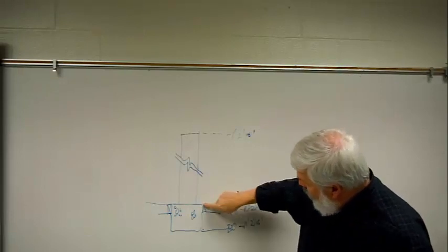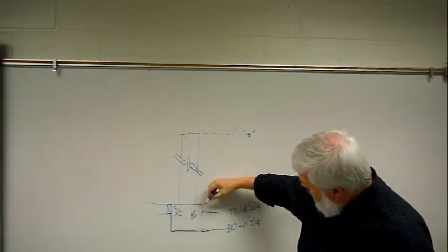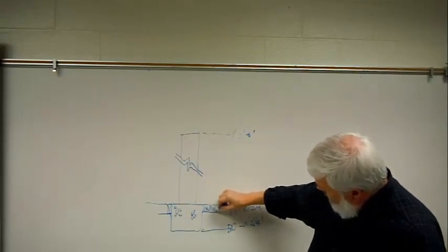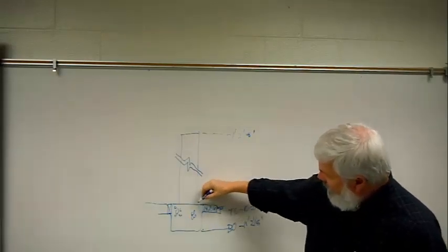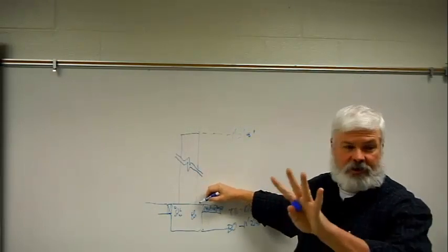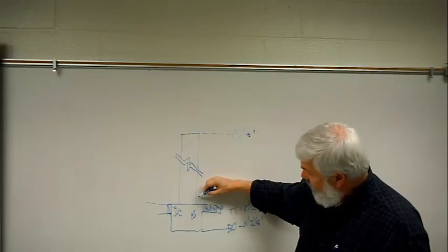You pull these form boards off, and you bring in 4 inches of gravel. And then on top of the gravel and on top of the footing right here, you pour 4 inches of concrete slab.